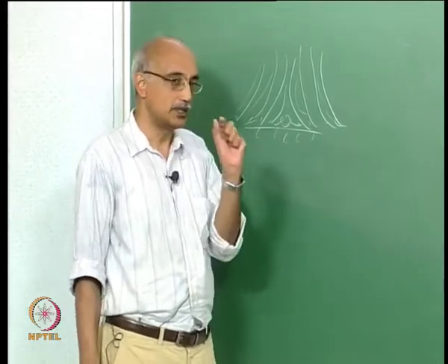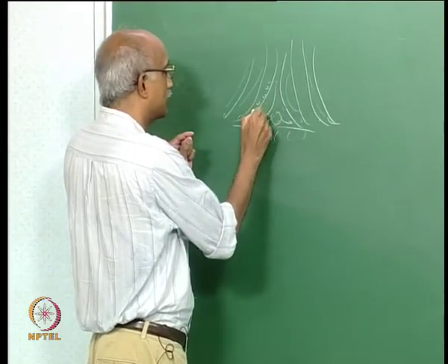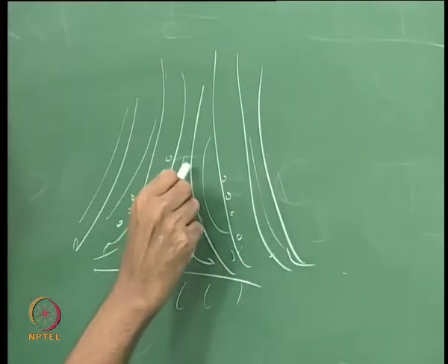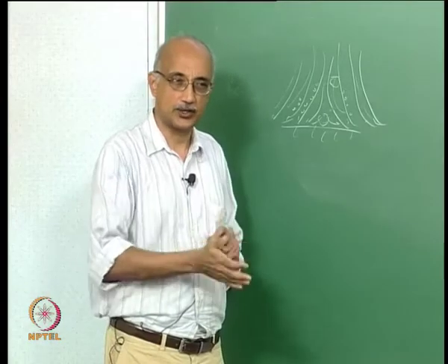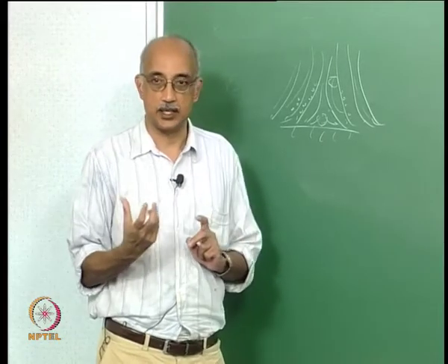But as you keep increasing particle size, fine particles may follow the streamlines. But what if you have a particle that is this size? Is that also going to want to follow the streamline? No. It's going to want to separate itself from the fluid streamline and follow a different trajectory, and that is because of the inertia that it has.